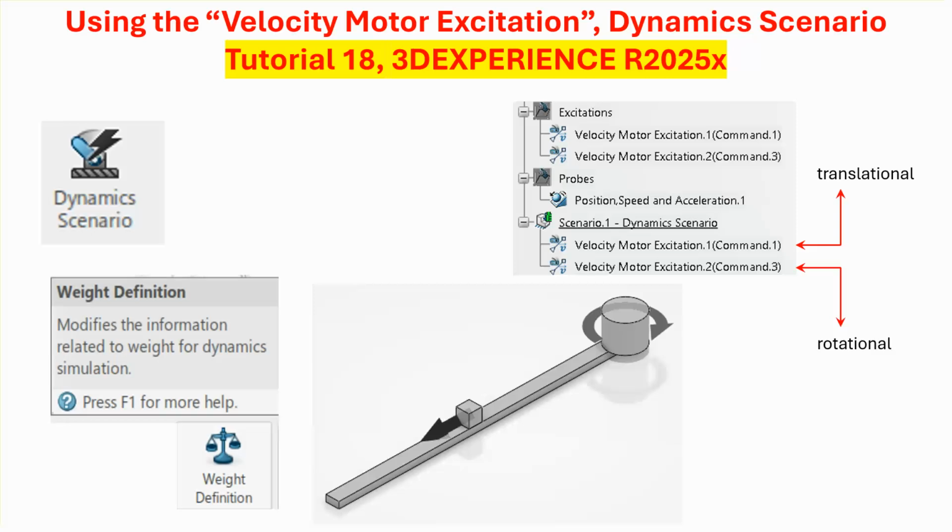Now, because this is done in dynamic scenario, you must assign the weights and or mass of the parts involved. You cannot use these motor excitations in kinematic scenarios.